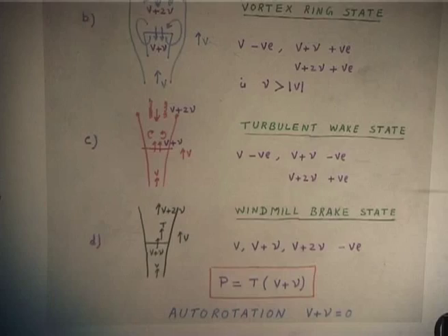So, the loss of potential energy is actually converted into the kinetic energy in spinning. Suppose if more is converted, it will start spinning faster. We do not want that situation. That is why this condition is very, very important in helicopters, because it is called auto rotation.